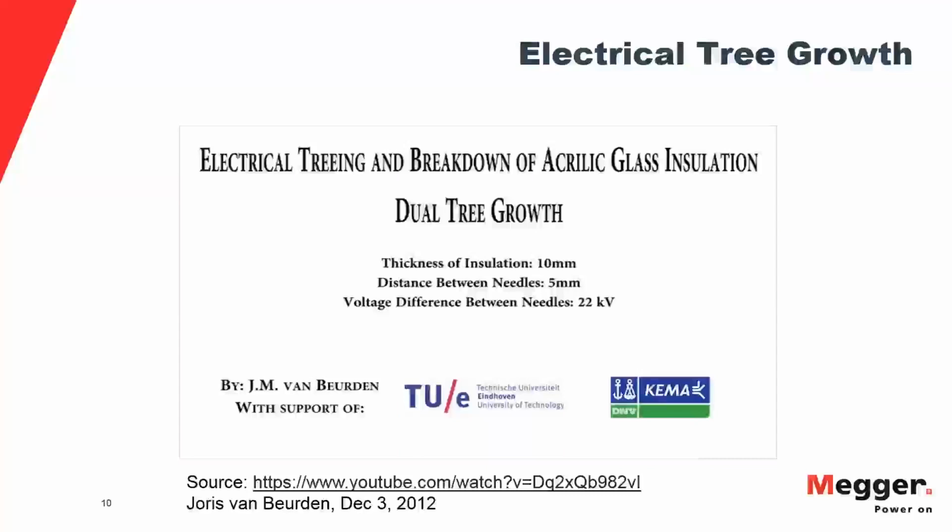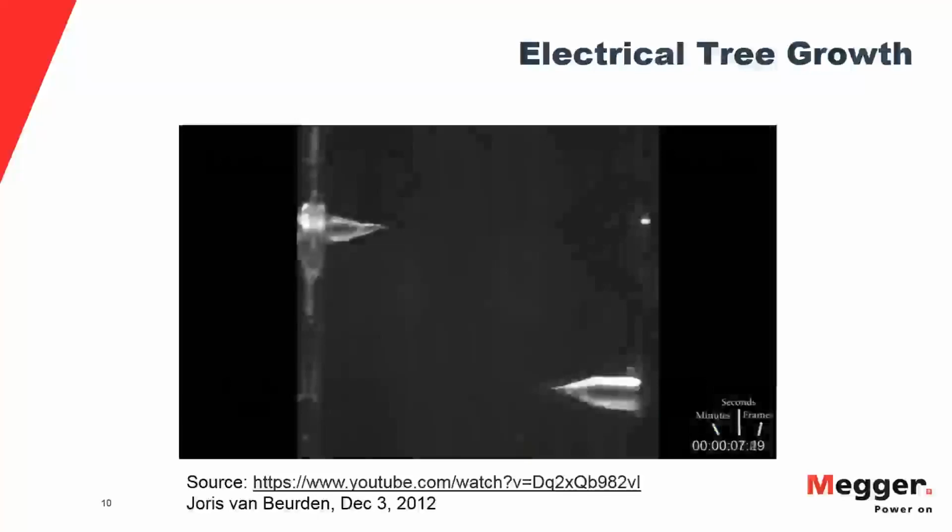And all of these stripes going through the cable are places where that tool scraped the insulation, and they're all experiencing partial discharge. And finally, in the top right, we have an example of a misaligned splice, where you can see that the crimp body of the splice was outside of the black Faraday cage of the splice body, and that caused, of course, partial discharge. And as you see in the picture here, that's how the splice was found, with that crimp outside of the middle of the splice.